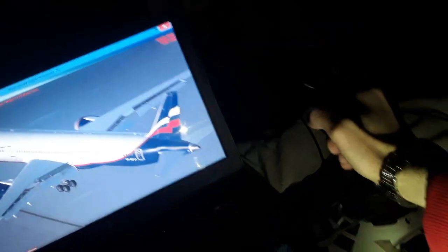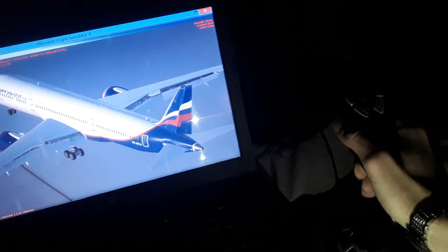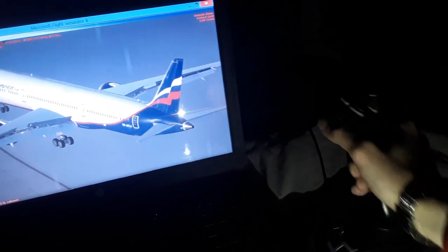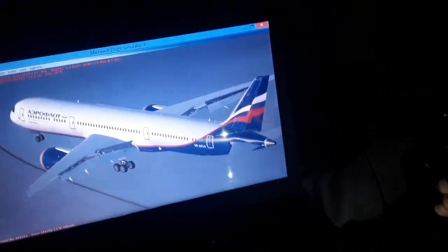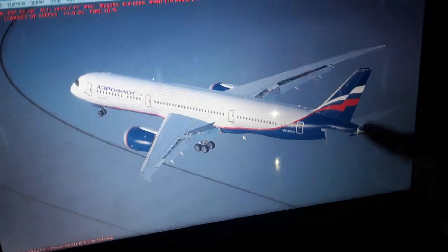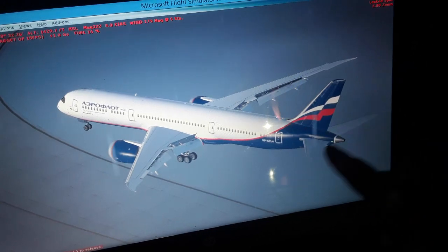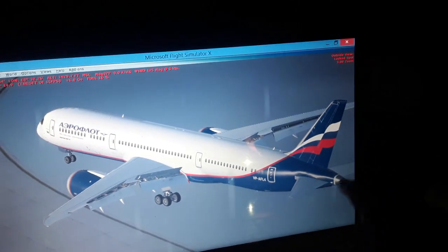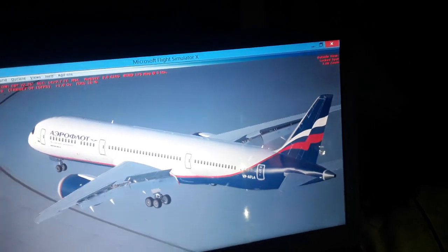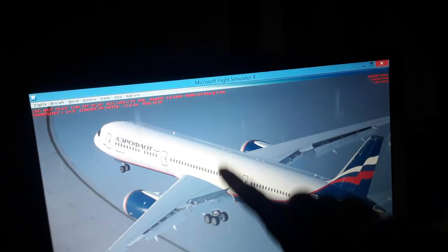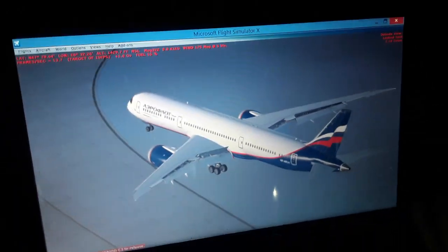So we have ailerons, spoilers, and so on over here, also the flight controls, to make turns in flight. We can climb and descend also using the elevator from the tail. Use the horizontal trim stabilizer. So we have the lateral axis from wingtip to wingtip, the longitudinal from nose to tail, the transverse over here, the horizontal tail of the aircraft. So you can trim up or trim down the aircraft tail as you want to fly the aircraft, to balance the aircraft in flight. So we have the longitudinal axis from nose to tail, the lateral from wingtip to wingtip, and the vertical transverses the center of gravity over here.